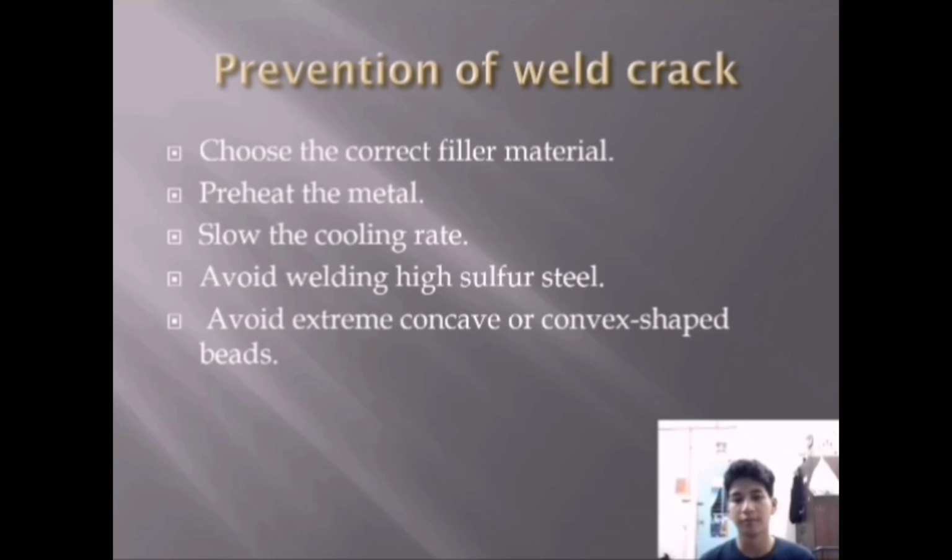So the prevention of weld crack. The first one is to choose the correct filler material. The second one is to preheat the metal. The third one is to slow the cooling rate. The fourth is to avoid welding high sulfur steel. And lastly is to avoid concave or convex shaped beads.